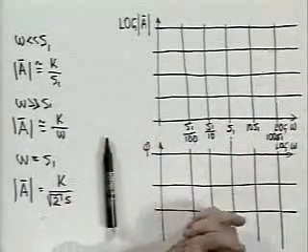You can see right away that one of the advantages of using Bode diagrams with a log scale for frequency is it allows you to display an extraordinarily wide range of frequency without crowding at the origin. If we were trying to display omega on a linear scale, and we were interested in behavior over 4 or 5 decades of frequency, to show that highest frequency decade, you would end up with the first 3 or 4 decades all crammed in right next to the origin, whereas the logarithmic scale spreads it out.